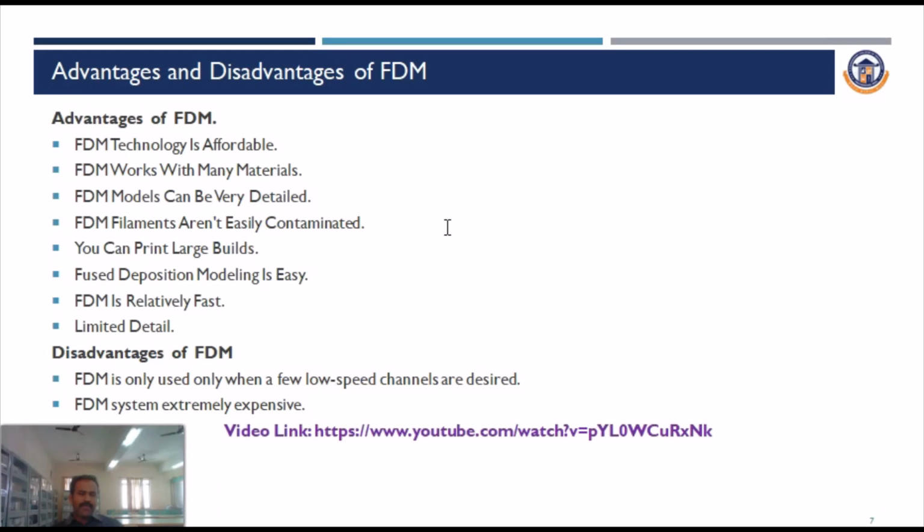So, take-home points. In FDM, fusion deposition modeling, the principle is that we supply two different types of material in liquid state. One is a build material, another one is a support material. Both are joined in a liquefier head. When the user defines whether the supply material, support material or build material is needed, once the build material is needed, the liquefier jet supplies the build material onto the base platform. The first layer is completely manufactured, then the platform moves in the Z direction and the next layer is started. The cycle is repeated until the full project is completed.